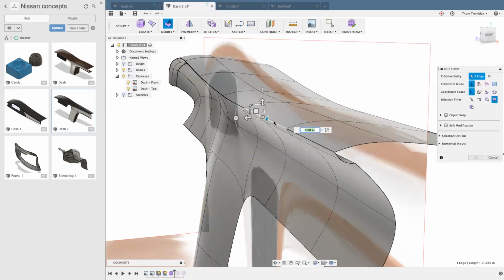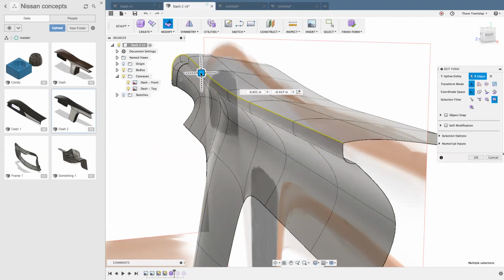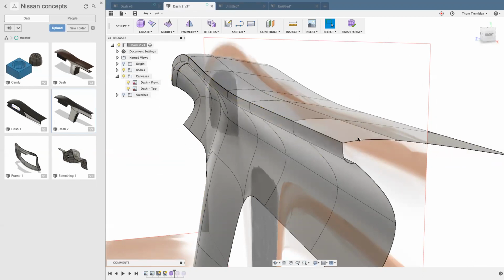Now, if we take this edge and go out to a solid model, once we have this enclosed, this is a perfect example of where using tools like the fillet or variable radius fillet that's built into Fusion solid modeling will give us a great deal of control. Using the G2 continuity that's just built into Fusion, we might have to go through and create a lot of extra edges close to each other to try to get that transition that we want. Sometimes if we just want a consistent tangent, or even a consistent rounded edge, the solid modeling tools can work a little better for us.